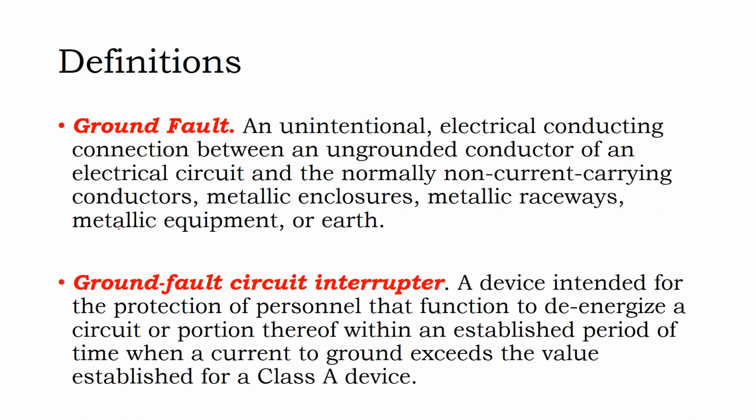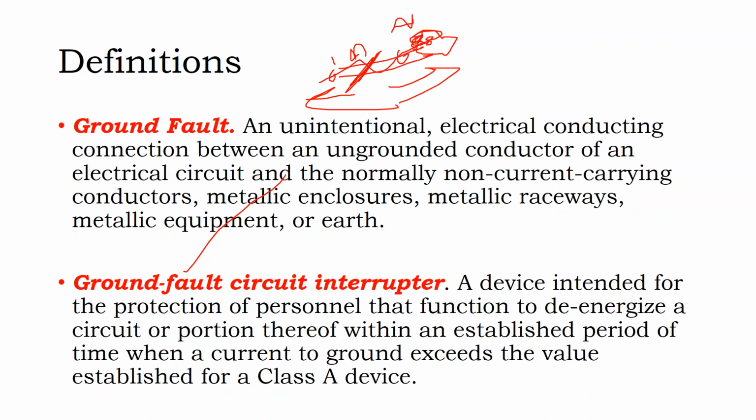And a ground fault is when you take an energized power line. So here's your solar MC4 connector. Let's say that connector is not made up tight and you have a fault here. Or let's say this cable is inside some conduit, a fixed rigid metal, and thermal expansion is causing that metal to pull apart, and all of a sudden this cable breaks and it's faulting into the metal, and that metal is connected to ground, and so that fault is clearing into ground.